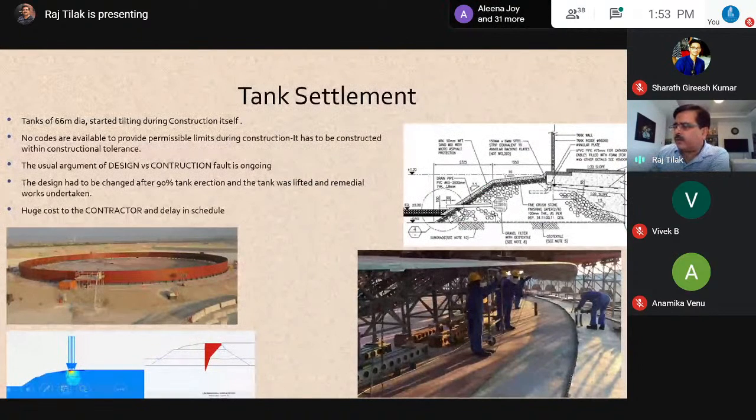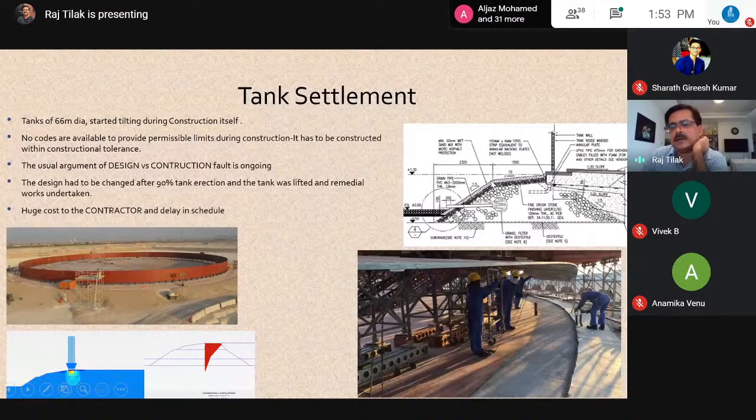And continuing on the tanks, if you look at the foundation of the tank, which is shown here on the right hand side top figure, a crushed gravel foundation type is proposed. It can have this type, it can have a concrete ring foundation. It can have different methods and different ways of resting the tank. In this case, it was this one.